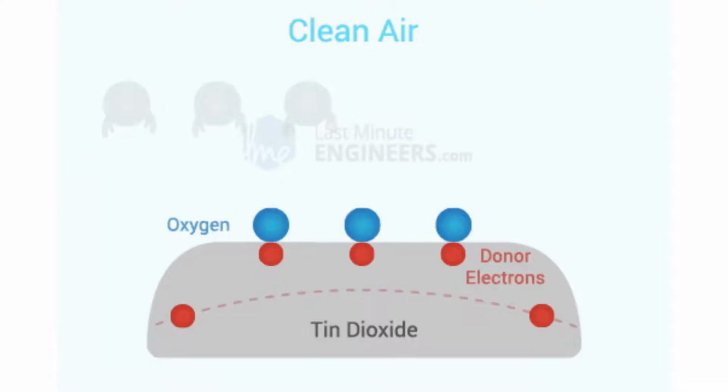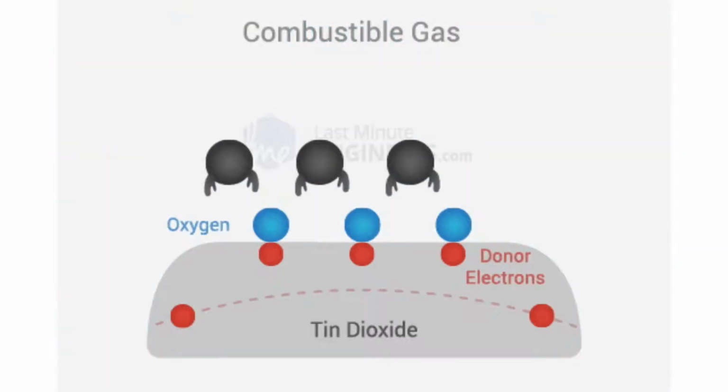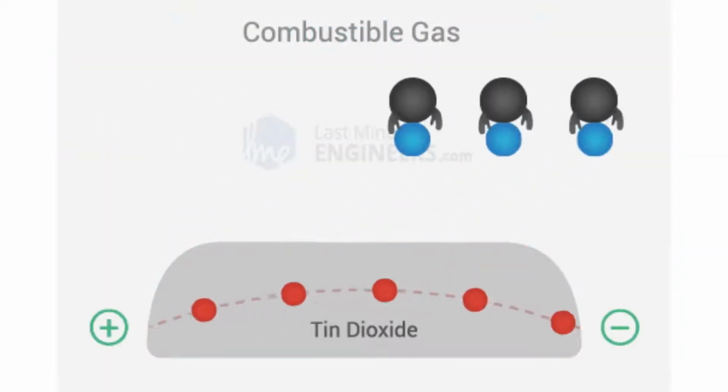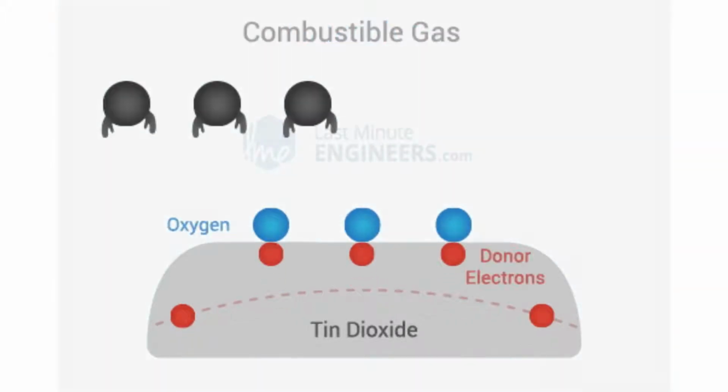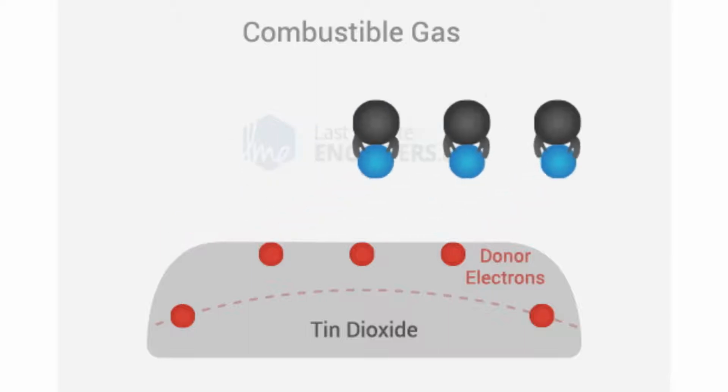The detection of hydrogen is based on change of resistance of the sensing material when the gas comes in contact with the material. Using a simple voltage divider network, concentrations of gas can be detected.